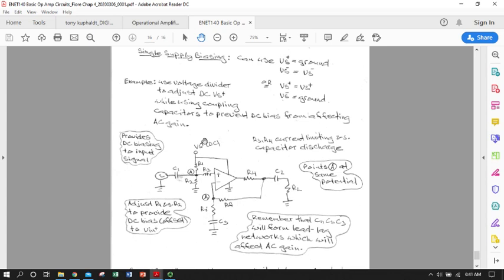And be aware that most op-amps are going to be current limited. And again, you'll see the 20 milliamps max output on quite a few devices. Not to say there aren't some that give more, and certainly there's probably some that give less. So back to read the spec sheet.